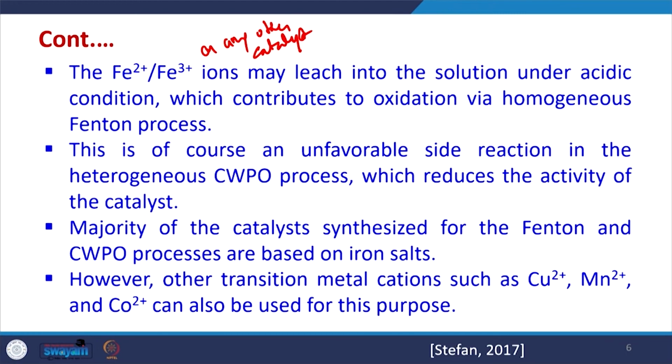This is of course an unfavorable side reaction in heterogeneous CWPO, which reduces the activity of the catalyst, because with time the catalyst amount will decrease, the activity will also reduce because the leaching is happening, and in addition the metal is going into the water, which may not be desirable. So, the majority of the catalysts synthesized for Fenton or CWPO processes are based upon iron salts, but any other salt can also be used. So, other salts include copper, manganese, cobalt, etc. They also have been reported for the CWPO process.